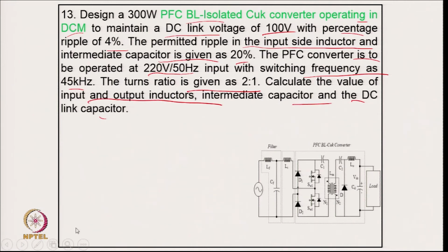So, this is typically a bridgeless Cuk converter. You can clearly see here that the input inductor and output inductor are shared, and of course all components are shared, with the energy transfer capacitor and then the transformer. For DCM we can have 2 to the power 3 designs, with one continuous and the remaining discontinuous. We can design even only one element as discontinuous in this converter, and that can also give the same performance as inherent power factor correction with the voltage follower approach.